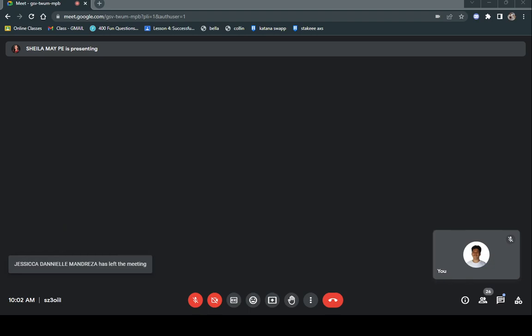So, for VGS, we use the VGS equation. 2.16 minus 1,100 times ID, which is 3.32 times 10 to the negative 3. So that's 1.79.